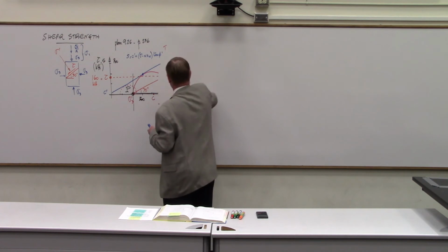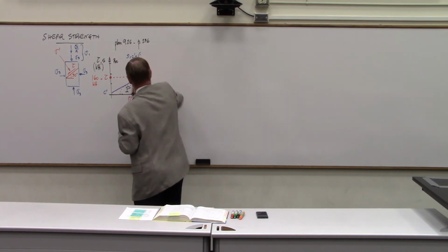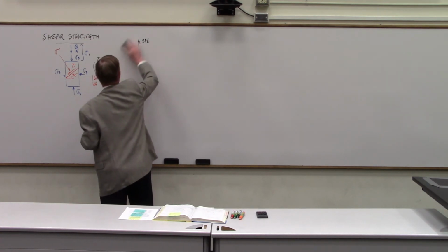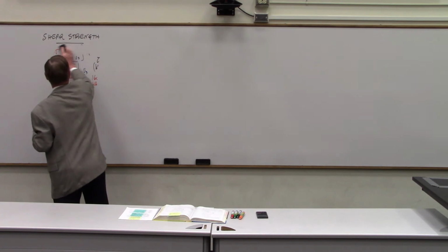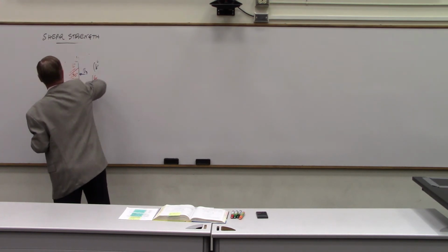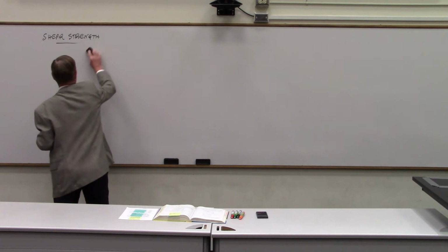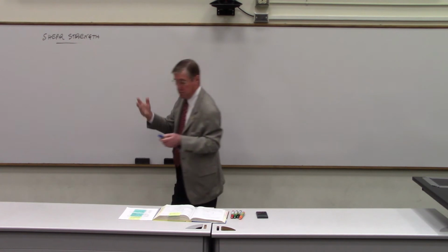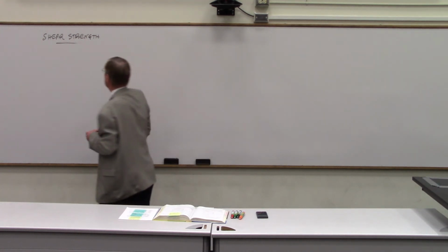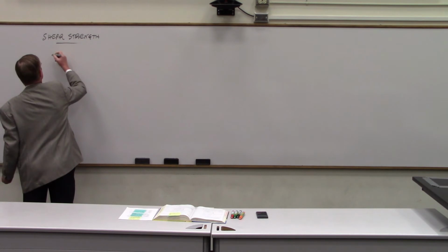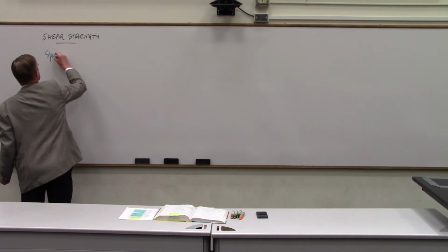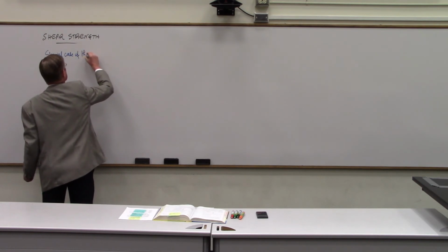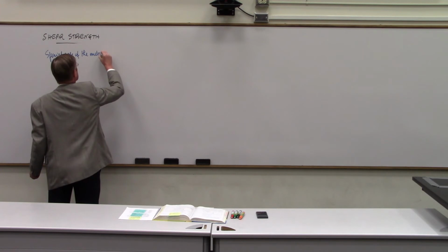So soils like silts and clays that typically, when you load them fast, don't have time to drain, at least for a good while. So that would be the case, for example, right after construction of a major structure. So we'll write it here, special case of the undrained shear strength.